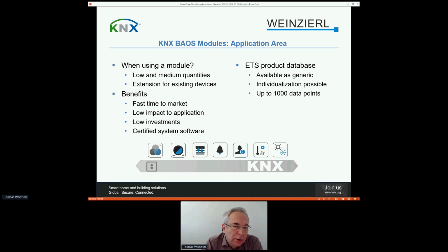Application areas for modules is always a question: is it a good solution to use a KNX module? A module is always a very good solution if you have low and medium quantities. It's also a good idea if you want to extend an existing device with KNX connectivity. Think about an existing device that may have a high volume of code, which should be combined with an existing stack and software. This can be a challenge.